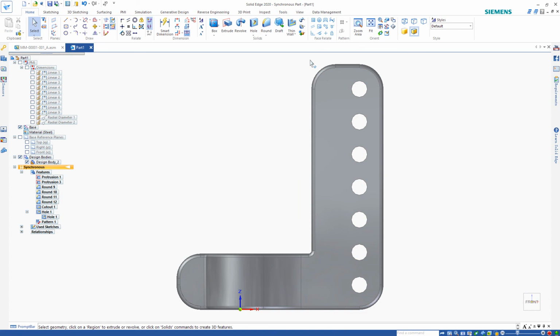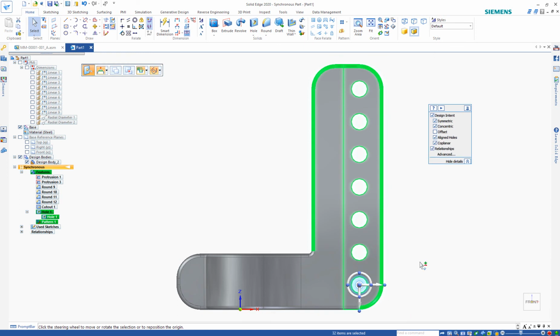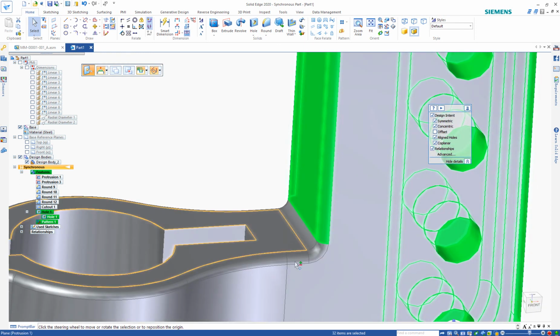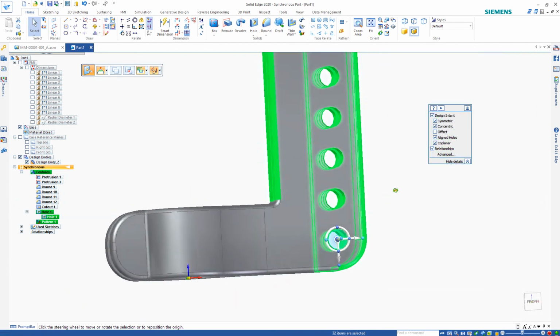First thing you want to do is select all the features that you want to tilt, like this. Okay? Make sure you didn't select this round, otherwise when you tilt it, the top surface will be changed too because they are all connected. Okay? Then